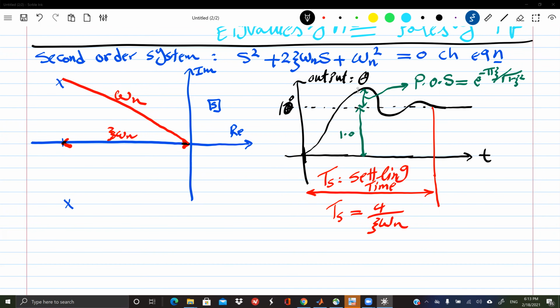But in the middle, during the excursion, I overshoot to say 15 degrees. If you have 50% overshoot, if you computed this and find it 0.5, then this is 50%. So if this is 10, this will be 5 degrees, which means what? I will eventually arrive to 10, but during the excursion, I will touch 15 degrees. And if this is your stall value, then you stall the airplane in the middle. So this is detrimental and catastrophic. So the overshoot is an important thing. Together, they are the main two parameters characterizing your performance.